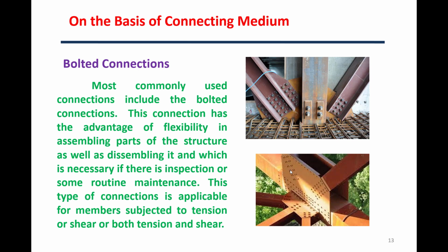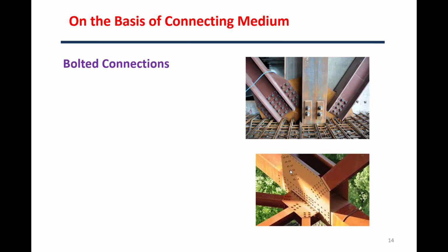So this connection has the advantage of flexibility in assembling parts of the structure, as well as disassembling it, which is necessary if there is inspection or some routine maintenance. This type of connection is applicable for members subjected to tension or shear, or both tension and shear.